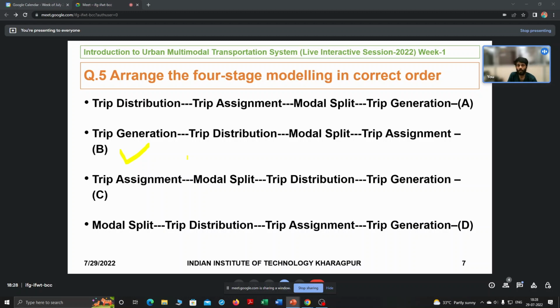So now if you have multiple zones, 3, 4, 5, 6, whatever the number of zones are, then for each zone, based on the data, you need to calculate the number of trips that a particular zone is generating, and the number of trips that a particular zone is attracting from other zones, right? Because if an area is an industrial area, then it will obviously attract more trips than a shopping area, right? If you have a zone around a shopping area, like that.